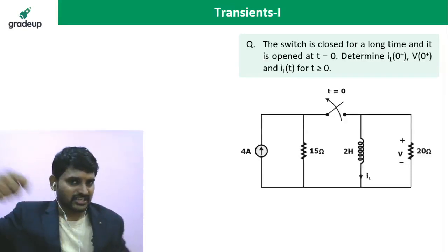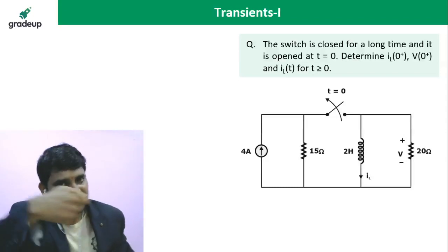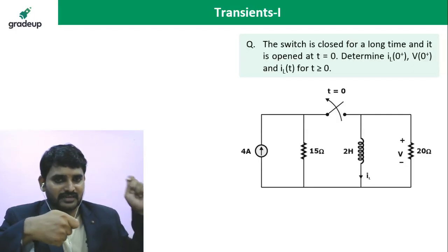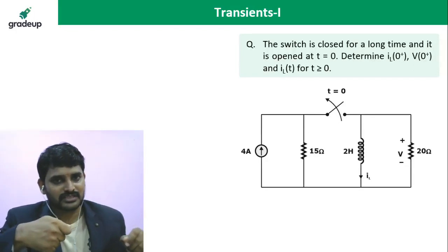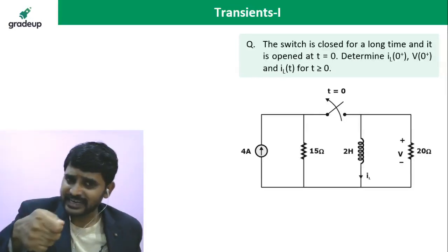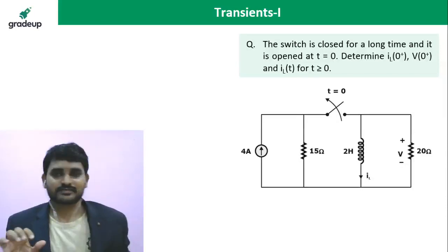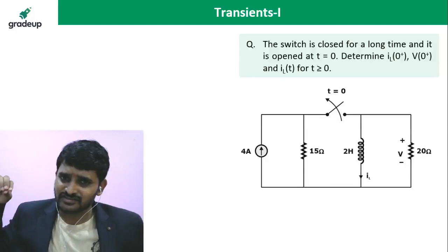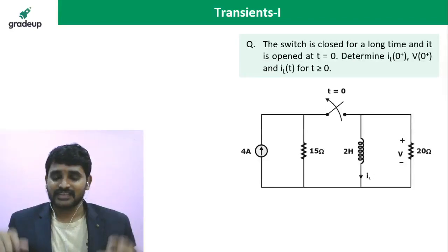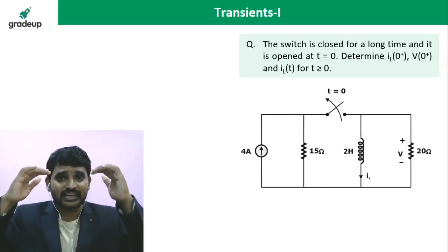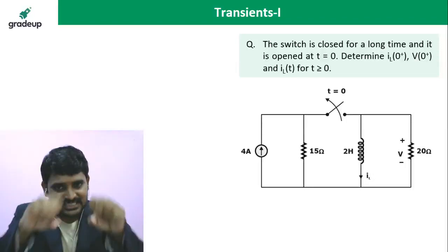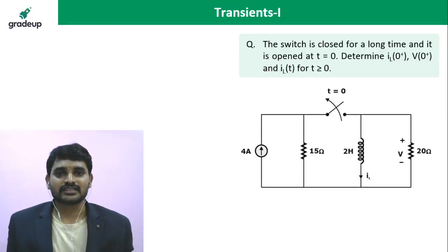Now, after discharging, you take that capacitor, separate the terminals and insert them in the socket. One terminal in phase, one terminal in neutral. Don't put the other terminal in earth, or put two terminals in one socket. Then the moment you insert the capacitor, you will feel the rush of electrons. A lot of electrons will get into the capacitor because the capacitor plate is already discharged, and they sit on the capacitor plate. That is charging. That rush of electrons, you can also call it transient current.